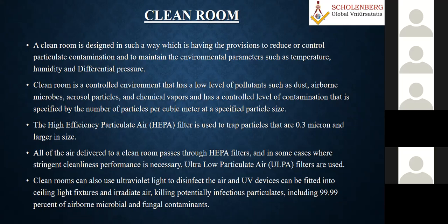That is how a clean room air conditioning system is definitely different from normal comfort air conditioning. I can even include operation theaters, and ICUs are also a type of clean room, but they have a different class level. We have already done a very detailed study about the different kinds of filtration: pre-filter, fine filter, HEPA filters, even alpha filters and all. And in some places we even use ultraviolet to disinfect the air. The ultraviolet devices can be fitted to the ceiling light fixtures and irradiate air, killing potentially infectious particles.